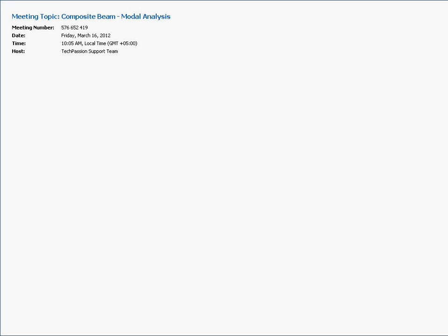As you may know, experimental modal analysis is done in many different ways. The example I showed was done with an impact hammer. You could do it using a shaker. There again, when you use a shaker, there are different types of signals that are used to excite the structure. Then, depending on the number of sensors and the number of exciters you are using, you could have MIMO testing, SIMO testing, single input multi-output testing. Then analyze the data and also compare it with your finite element analysis results.